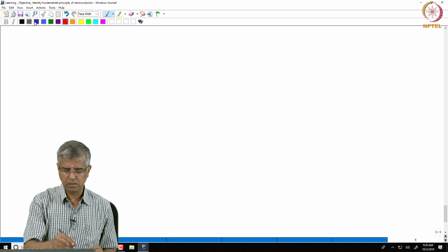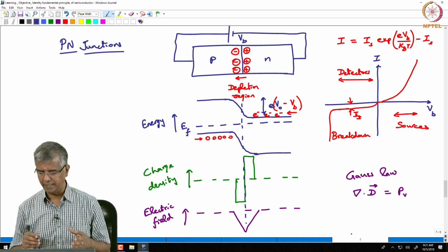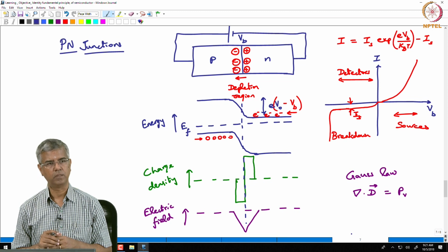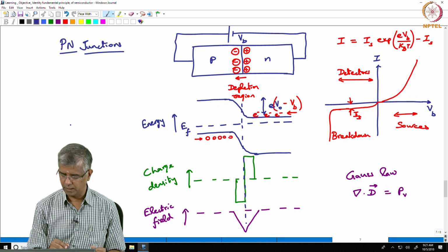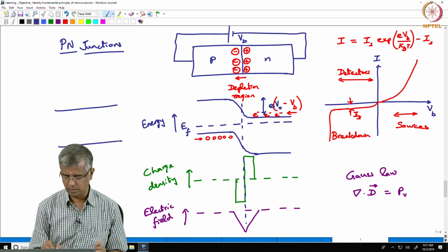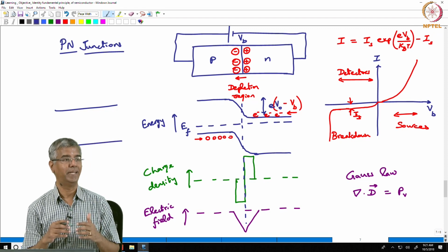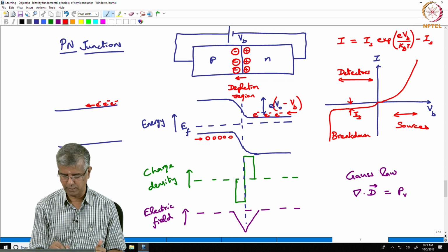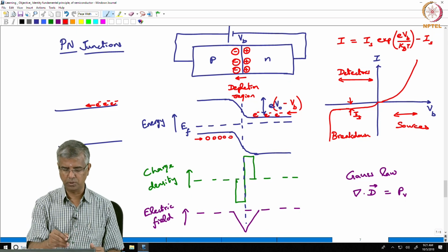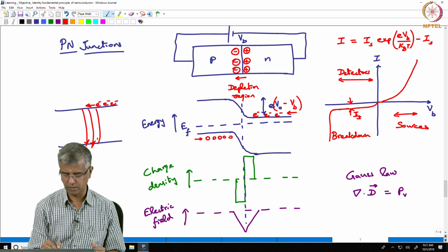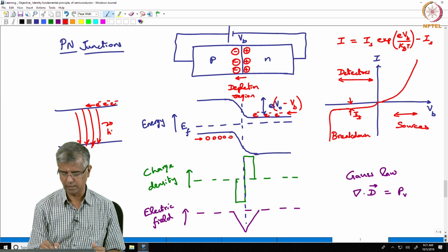It so happens that when you talk about light emission, when you are talking about recombination of electrons and holes, effectively under certain forward bias conditions, your conduction band and valence band are aligned, and so you have all these electrons going from here and all these holes that are injected from here, and then you could have recombination events happening over here, which results in light emission.